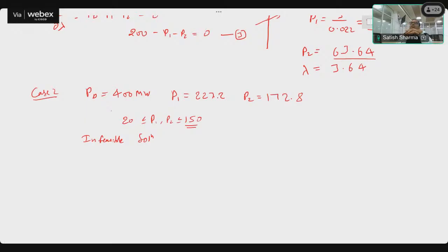Yes, inequality constraint needs to be enforced. It is quite evident that with only two generators, we can never supply more than 300 megawatts. But whose fault is it, that demand is 400 and there are only two units, and both of these units are not able to supply it? Yes, one comment is there: unit commitment. Thank you, Satya. So it's basically the system operator's fault. If demand is more, he should have foreseen it and committed more units.